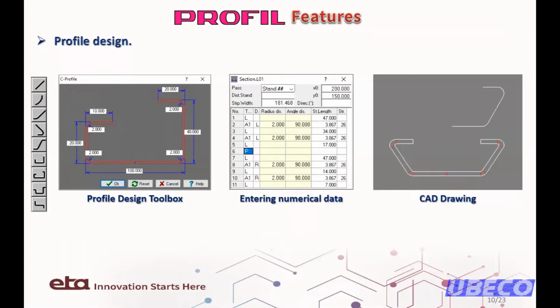You may design a profile using 3 different approaches in Profil. First, we can use a profile design toolbox where there is a parametrics window that allows you to key in the values of each line segment and the radius.